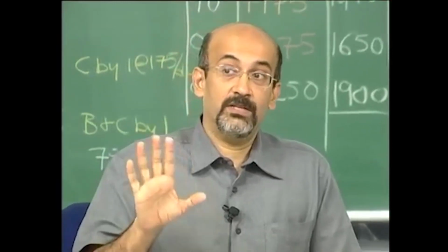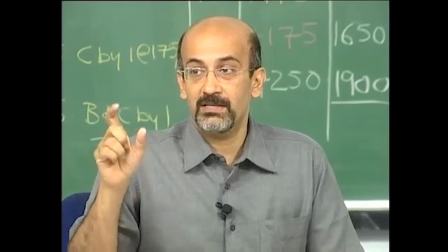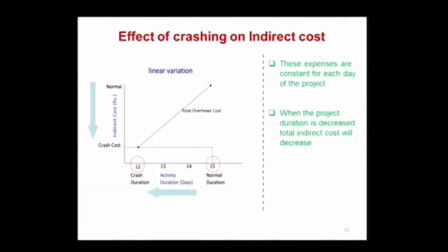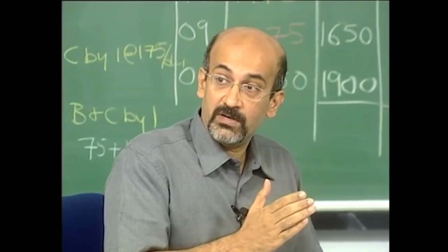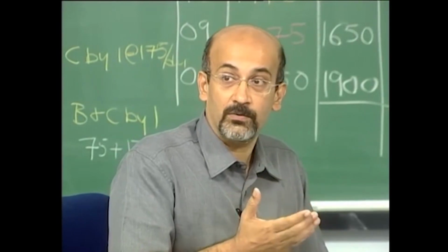So what I am saying is that on a daily basis I will pay the same amount, the rate per day is about the same. The total will obviously change, but my rate per day is the same. And if I take the rate per day the same, and start increasing my project duration, what happens? Cost goes up, and if I start decreasing my project duration, obviously the cost goes down.